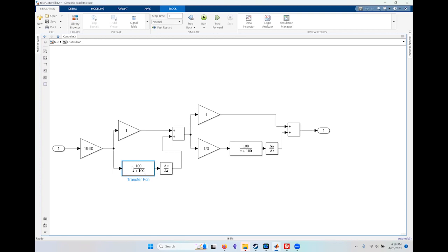Okay, so in this case, we avoided this error due to the differentiator by having the filter come before the approximate differentiator. Okay, so this is bonkers. Analytically it shouldn't matter, but because this is an approximate simulation, it does matter. And because this guy is bad, it's not good to use this delta u by delta t in a numerical simulation, right?